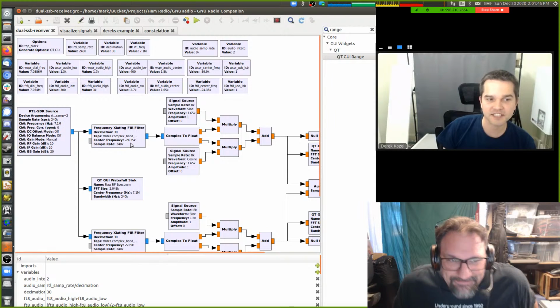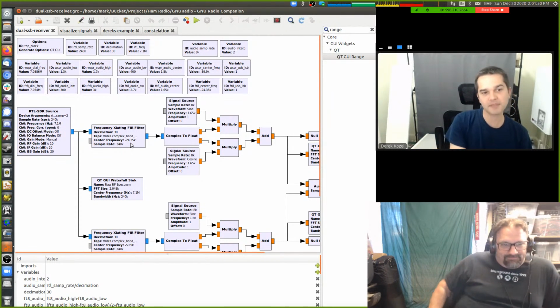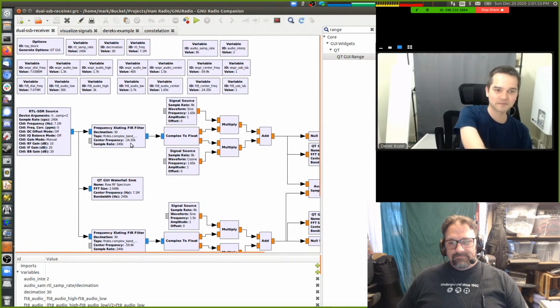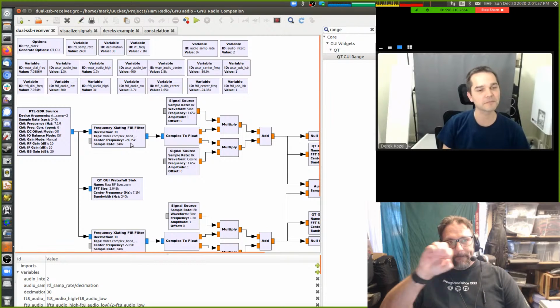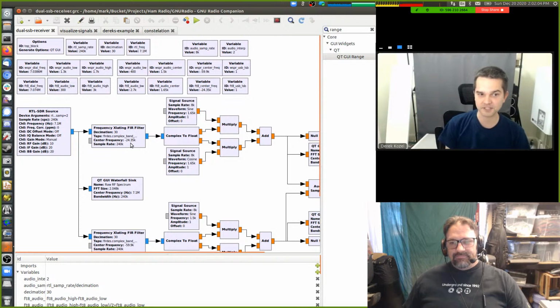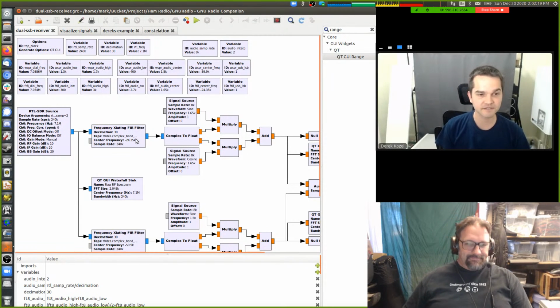Anyways, it is relative to that 7.1 megahertz. So we're going to shift basically up. We're going to grab that. It's basically like you were grabbing the x-axis at negative 24 and dragging it to 0. Over to 0, yeah. And we have seen that work with just a multiplication by a synthesized local oscillator. So is it literally just generating a minus 24.35 kilohertz LO and mixing them? Fundamentally, yes. Okay. It's doing it in a computationally efficient way. Okay. But yes. Okay. That is what it's doing.